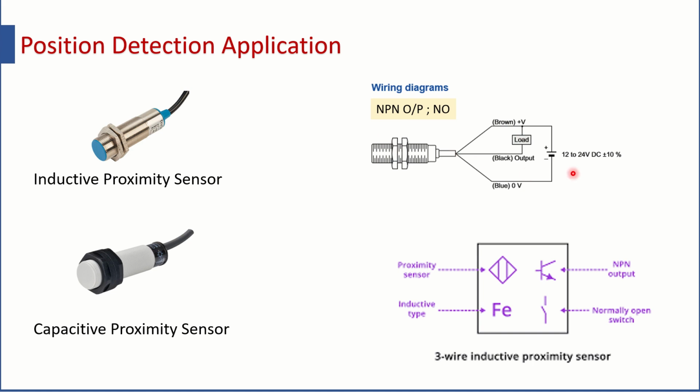Again, you can find that the supply that you can apply for the sensor is 12 volt to 24 volt. Now you can see what a wide range of voltage you can apply to the sensor. So this is very important. Most of the industrial sensors nowadays can accommodate a large window of supply voltage, and therefore it is very flexible to connect them to any of the operations.